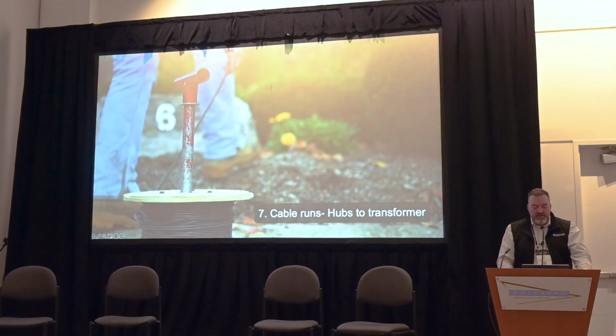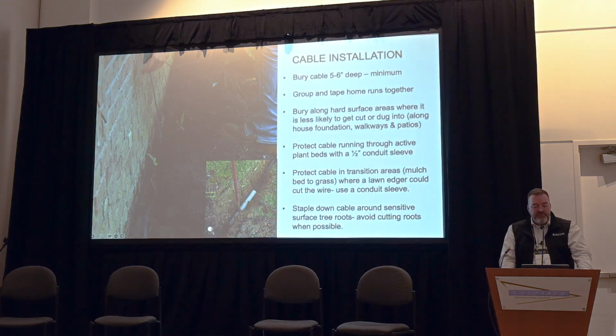So as they're coming in, cable runs. Your techs are going to start running your cables to the transformers. For cable installation, I look at 5 to 6 inches minimum. 6 feet deep, that would be terrible. And then I group and tape my home runs together.